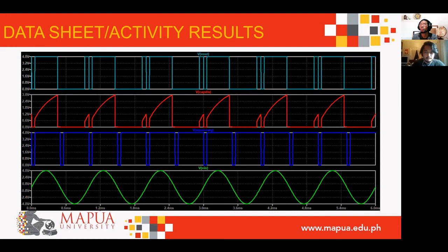So next are the PWM outputs. It is observed that the square wave has a higher duty cycle, which is almost similar to the baseband signal that is in unipolar form. It is like the negative polarity of the baseband signal is folded to the positive plane of the plot, with a small width of off state before another long on state. The discharge output signal is like a sawtooth, which represents the red line, with small and large irregularly shaped pulses. This is due to the charging and discharging of the capacitor.